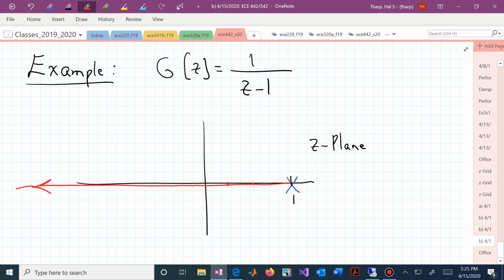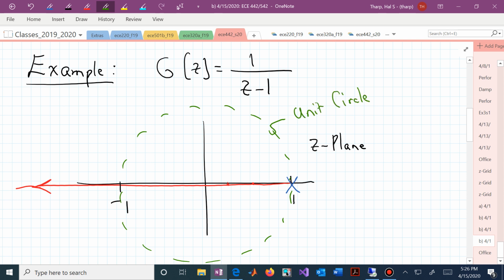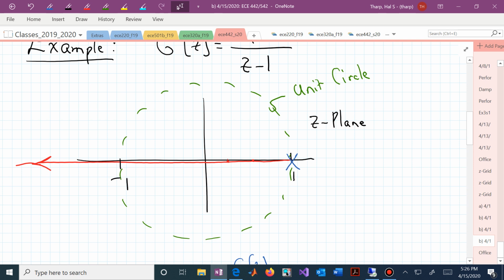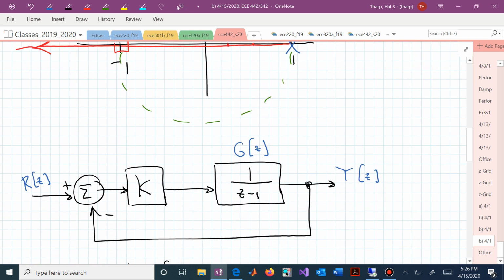That's now all potential closed loop poles, and we know that some of those, if we cranked up the gain too much, are going to go outside the unit circle. We are still worried about keeping all of our branches of the root locus simultaneously inside the unit circle. The way to do that is to make sure that you don't adjust that knob, that K value, beyond the setting that would produce a pole outside of the unit circle.